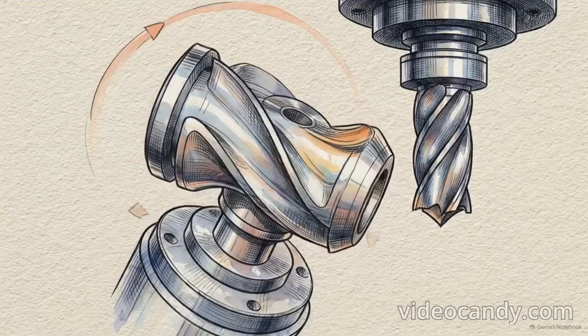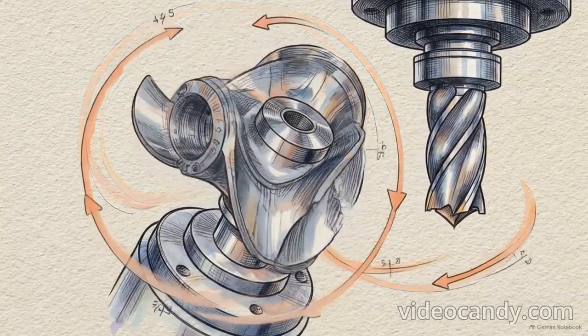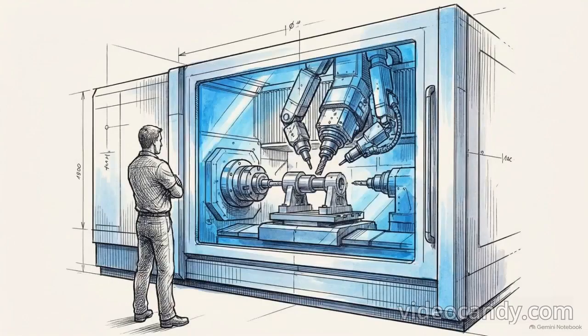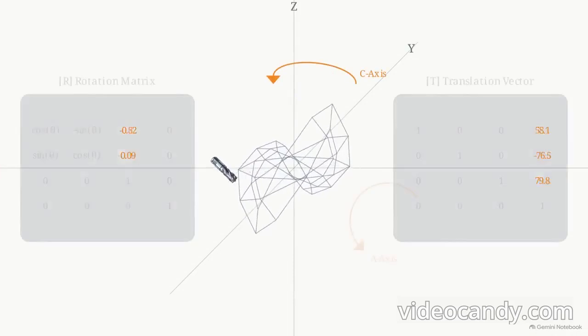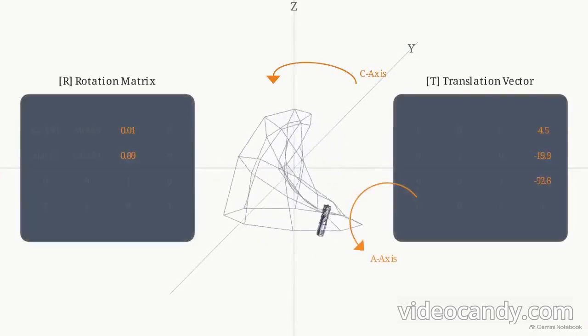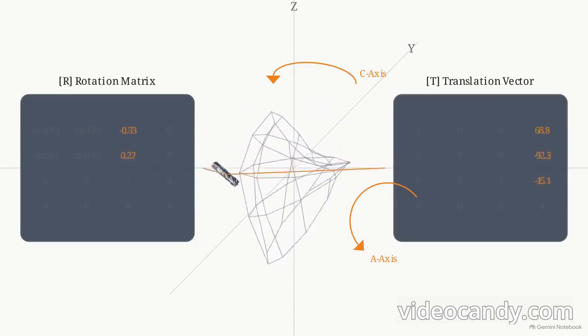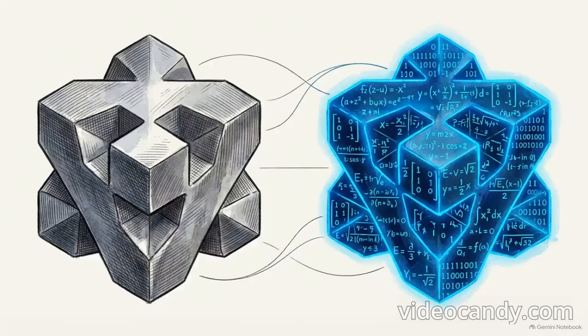Moving to 4 and 5-axis machining allows continuous rotation around the X and Y axes. This makes complex, aerospace-grade contours achievable without an operator ever stopping to reposition the metal. Coordinating 5 axes simultaneously requires serious processing power. The controller uses complex mathematical matrices, known as kinematics, to constantly calculate the exact required angle of the tool relative to a part that is spinning through 3-dimensional space. Multi-axis machining overcomes physical tool access limits by turning a stubborn geometrical puzzle into a highly complex, solvable math problem.